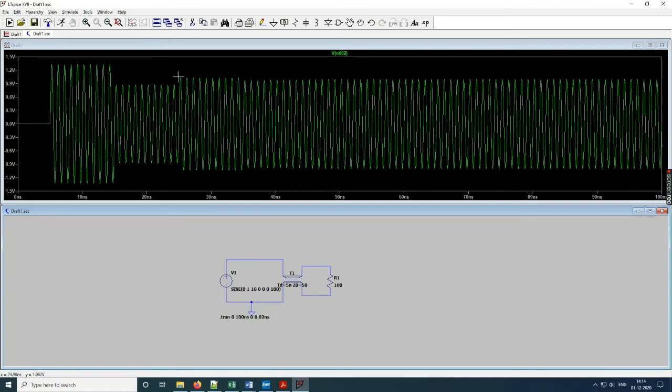So you can see these changes happen many times. You have high voltage, then low voltage, again a little high, again a little low, and after a point of time, it seems to settle down. The voltage you observe across the load, or at any point across the line, is a function of time, and it is caused not by one set of reflections, but by multiple sets of reflections.